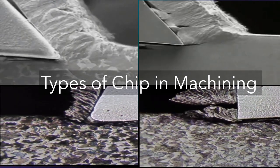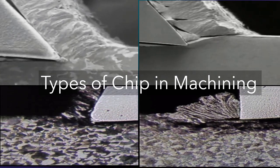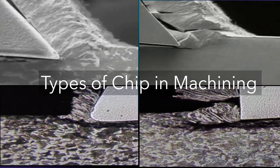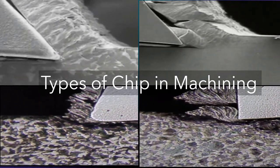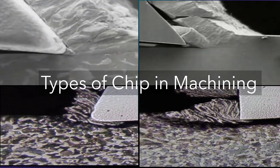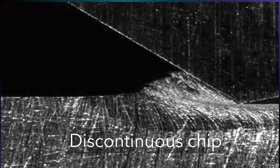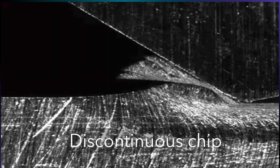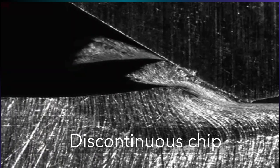The formation of the chip depends on the type of material being machined and the cutting conditions of the operation. Four basic types of chip can be distinguished. The first type is the discontinuous chip, where relatively brittle materials, like cast iron, are machined at low cutting speeds.